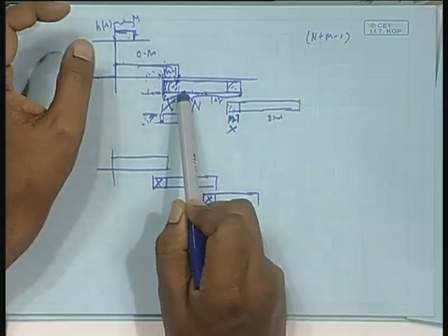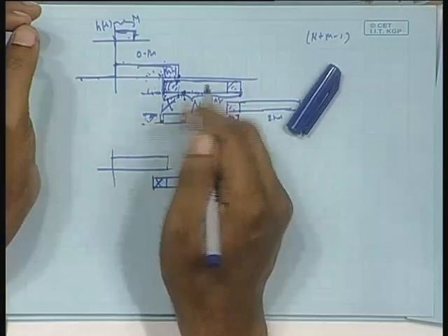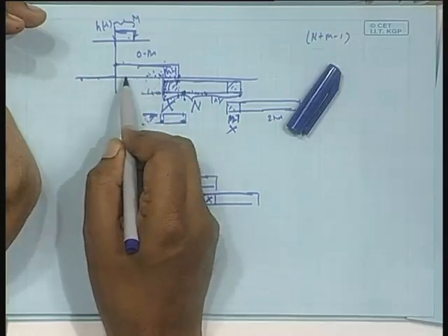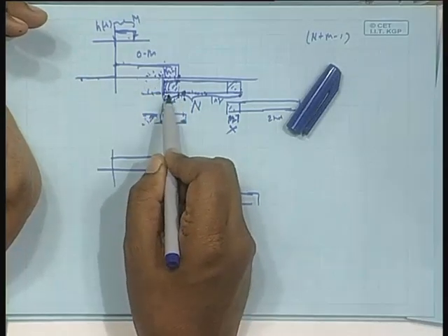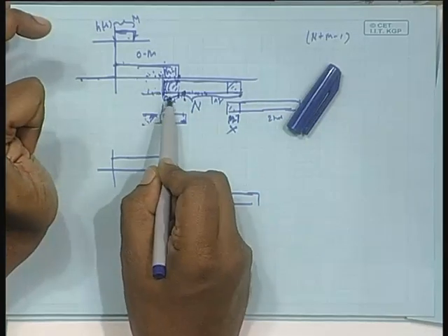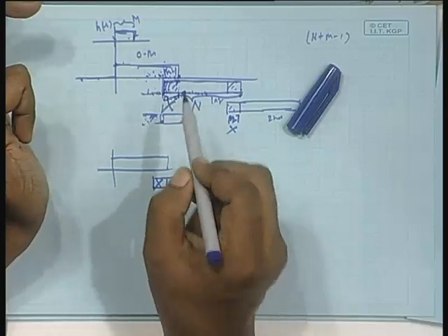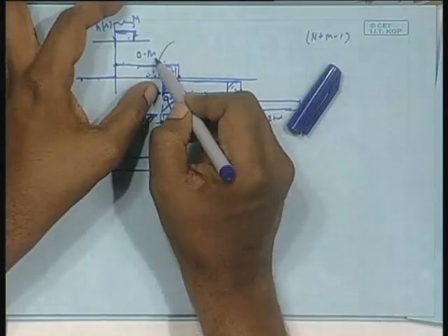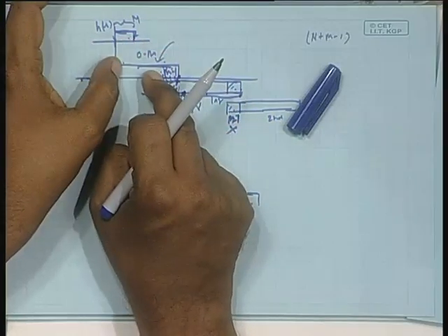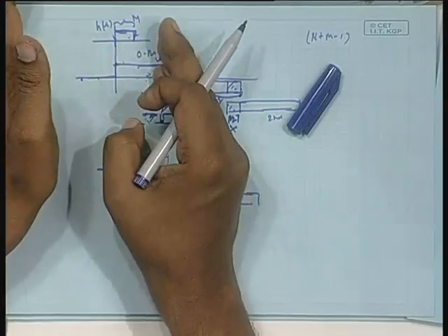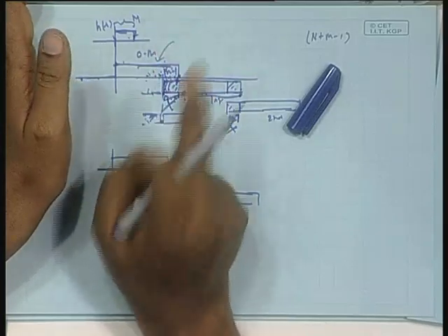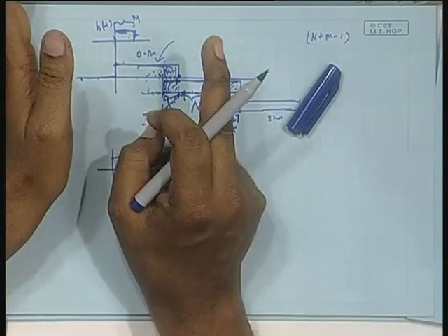At that time, from this point onwards, to get the output, I do not need any data from this block, because the previous m minus 1 samples available here are enough for me. Then what will happen for computing the output here? Firstly, if I have to compute the output at these points, I will target this block. These points come under this block, therefore the filter weight for this block, but that I have already calculated in the previous round, that I have saved. Are you getting my point?